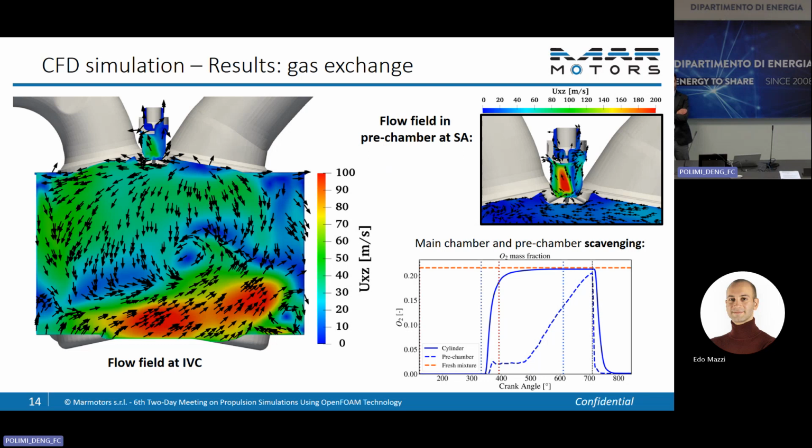And the hot pocket will just displace so much volume of the reactants. After that, the flame will propagate and burn the rest of the main chamber. That process is flame combustion. Once you get into that mode, you'll be hardly anywhere close to the high Karlovitz number regime. So your turbulent flame speed Peters correlation works just fine. So again, I don't mean to suggest this works for every condition, every different engine, but based on our experience, that is our conclusion. So you should never say no to a flamelet.